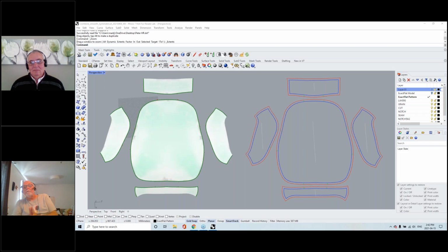So you would have probably an unacceptable error, especially if you're going round to meet something at the other side. As you noticed on the headrest, I went round the headrest and it met again on the other side. Now, there are ways of dealing with that. The first thing is don't do a complete path, start from a central point and go clockwise and anti-clockwise. That halves the path length.